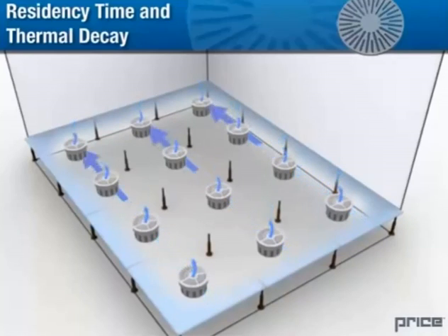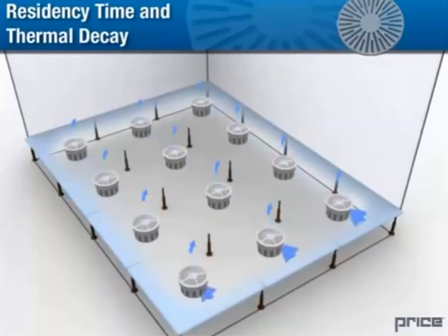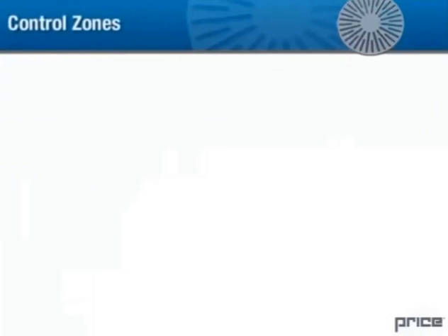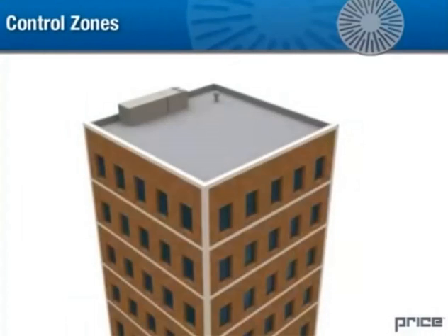It is important to promote the even distribution of air in the plenum and the ability to direct more air into local areas of resistance so that consistency in airflow can be achieved. Rarely do all areas of a building experience the same heating and cooling loads at the same time. Typically, there are up to 6 distinct zones in a building.